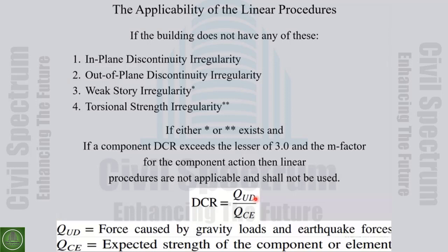If we test an ordinary reinforced concrete beam, we say that in bending it behaves in a more ductile way, because when the longitudinal reinforcement is yielded, then if the detailing is good, we can have a good plastic deformation before the concrete crushes and the failure happens.